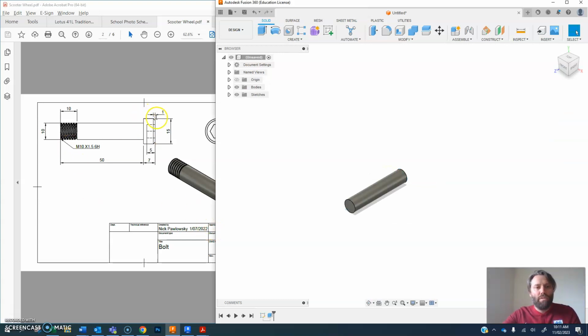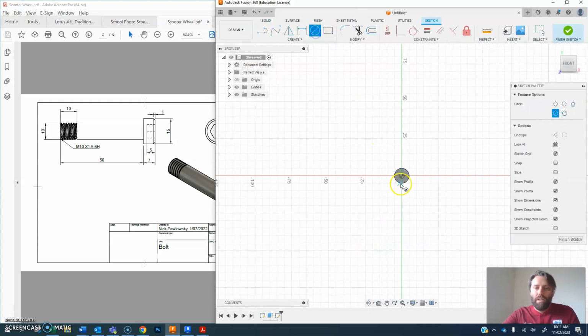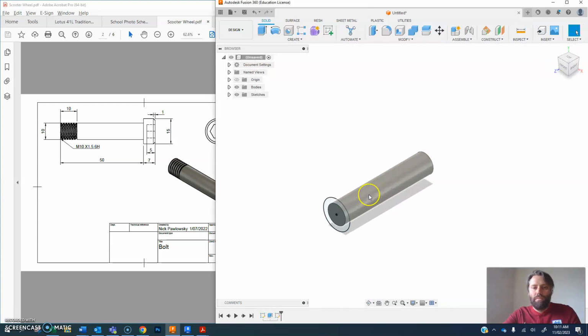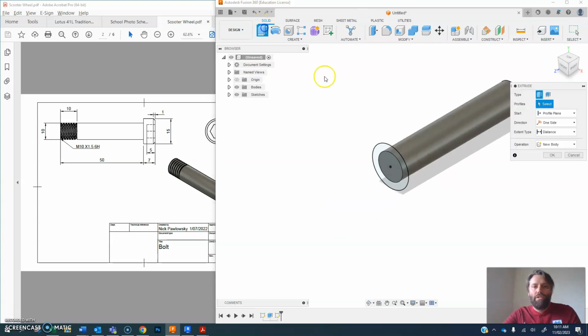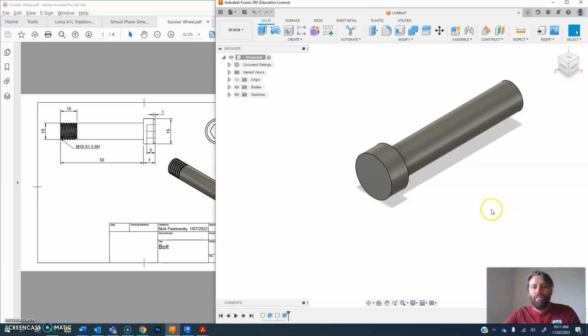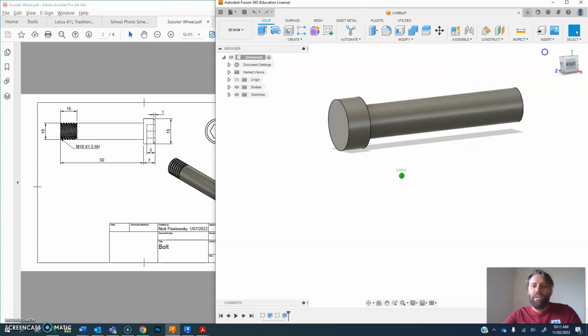And then I'm going to build my short fat cylinder, so that's going to be 15 wide by 7 extrusion. I'm going to start my sketch on the end. I'm going to build my circle, which is 15, and then I'm going to extrude that by 7. So now I've got roughly the right size and shape. I can add the other detail elements I need to this part.